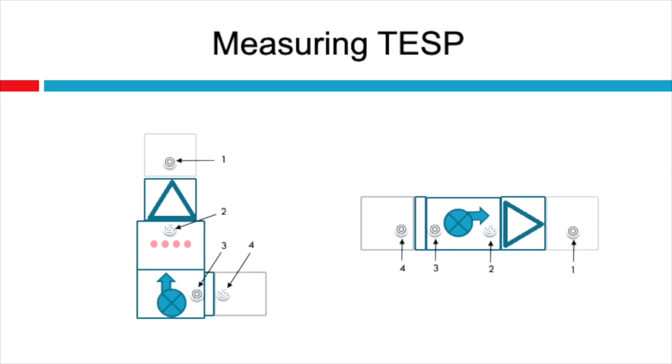If you replace that air filter on the return duct, you also need to measure in the blower section after the filter because that was not shipped in the blower section with the unit. When you add that, let's say MERV 11 or MERV 8, 4 or 5 inch pleated filter, you're going to want to include the pressure drop of that filter in your total external static pressure calculation. And what you're going to find most of the time, an A-coil add-on on top of a furnace with a really high-end air filter is going to have a higher total external static pressure than, let's say, a heat pump air handler, because all of the heat pump air handler is shipped in one box. In this last example with the furnace and the A-coil, you're going to want to measure in location numbers 2 and 3 if you have an A-coil and a different filter that's upgraded to the system.